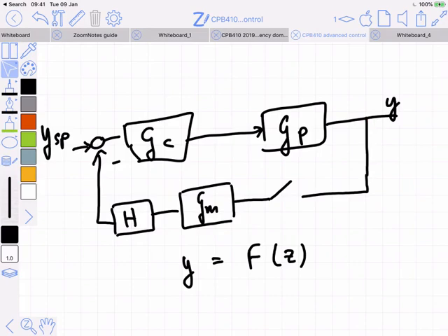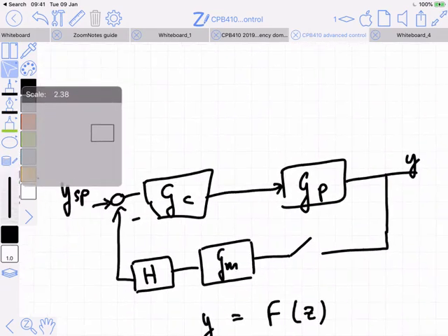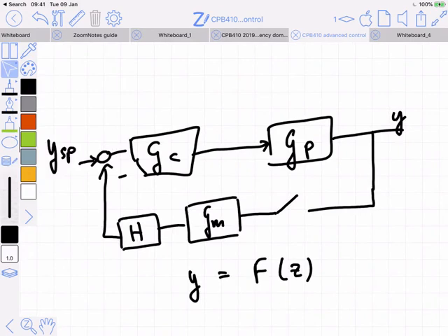So with discrete, there isn't always a transfer function the way that we know it, that relates the inputs to the outputs in that nice way where we can factor out the transfer function and the input, right? And it's because of this. So this is one version where we would want to use a discrete transform because we need to take into account that sampling is occurring, but where writing that as a transfer function is not possible. Does everybody understand what I've just said, right?